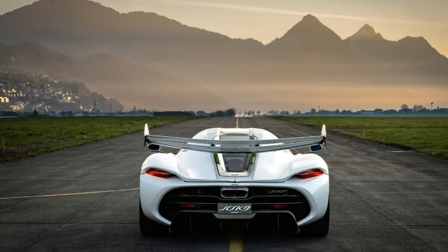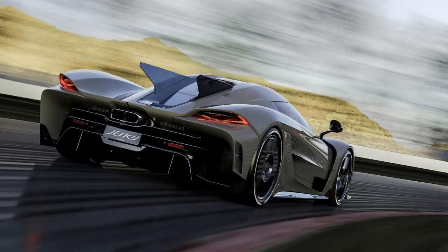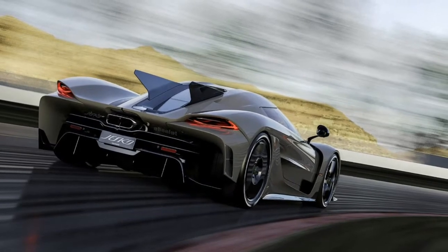So the car needs to produce more power for propelling forward with higher acceleration and to achieve a better top speed. So when designing a hypercar or a super sports car or a racing car, we have to make a compromise between downforce and top speed as well as drag. If we prefer downforce, we have less top speed. And if we choose top speed, we have less downforce.